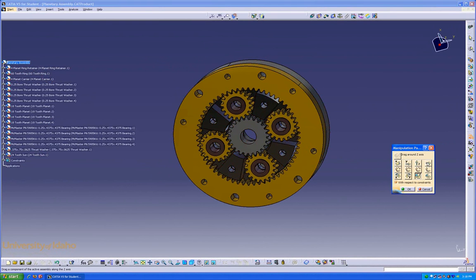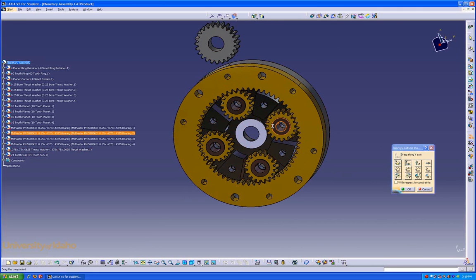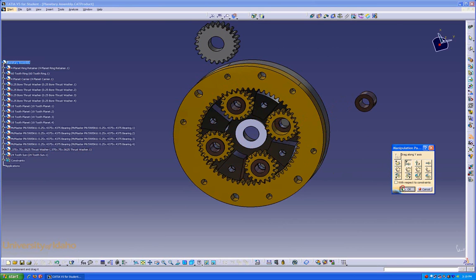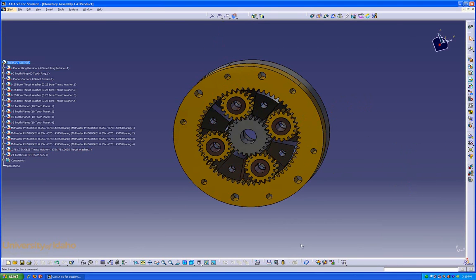The fourth selection allows you to drag along any plane, any axis, or rotate around any axis. For rotation, you need to select the axis that you'd like stuff to be rotated around. In this case, this middle one, and it'll select the part with the second click. The Respect to Constraints button allows you to move parts with respect to constraints, like we just did, or deselect it to be able to move parts in any direction. Click OK to exit, then Update to bring it all back.